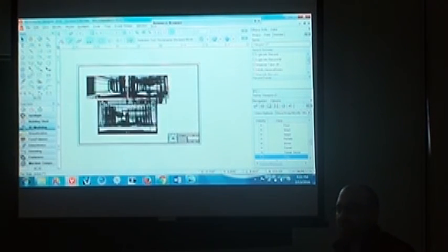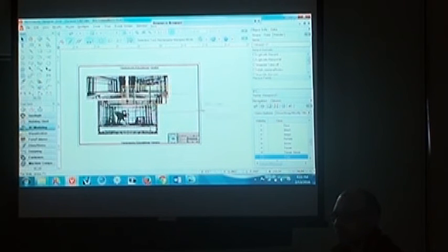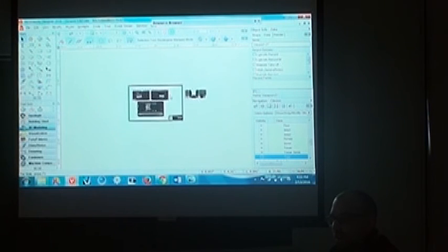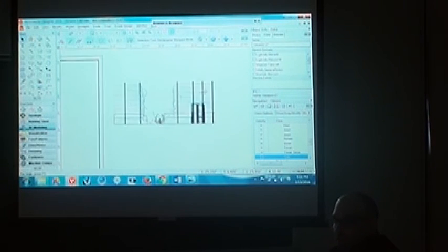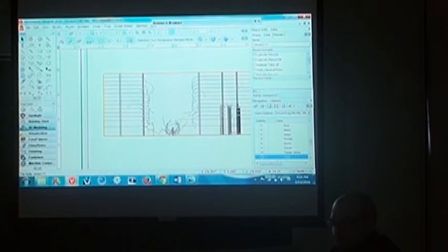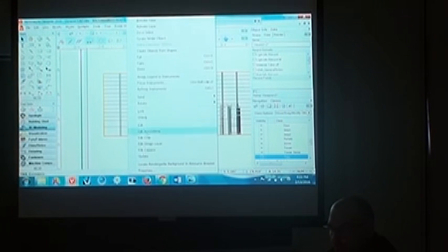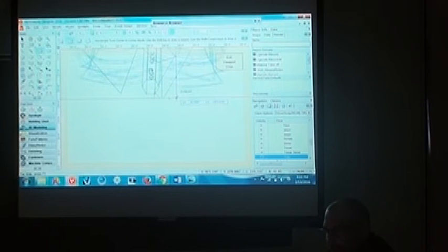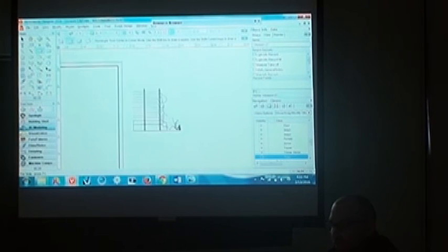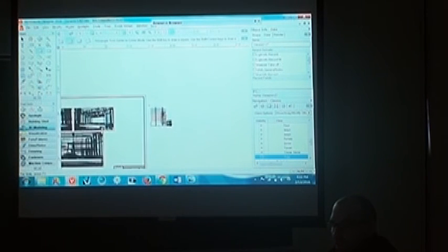And this is a drawing sheet I already had set up, so it has other views already on it, but this is the viewport that I just created. Right? And it took the view that I was currently in when I created the viewport, which is flat on that section of the fence. So what I could do now is right click, edit the crop on this viewport, and cut out, get rid of the other part of the fence. And now I have an elevation view of just that part of the fence.